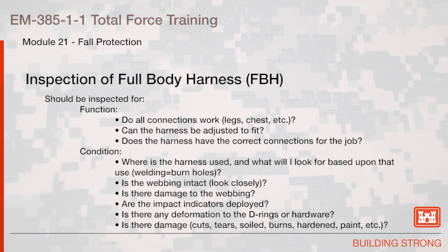Has it been used for welding, and are there burn holes? Is the webbing intact? Inspect closely. Is there damage to the webbing? Are the impact indicators deployed? Is there any deformation to the D-rings or hardware? Is there damage, cuts, tears, soiled, burns, hardened paint, etc.?